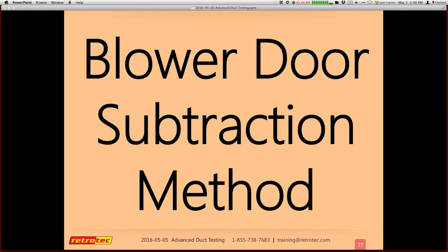I guess the thing you want to be careful of is that, before you ever perform a blower door test, you should be asking, does anybody in the house have any respiratory or asthma conditions? Even if you're going to do any kind of duct testing, you want to make sure, if you're going to do anything that could stir up conditions in the house, that you ask those questions ahead of time. I didn't cover that, but it's a reminder to do that. I don't know if the blower door test prior to doing a duct test makes a difference. I may be challenged in terms of doing a live webinar that I cannot answer that. So Colin may be able to help with that. If there's something different, I'll get back with you.